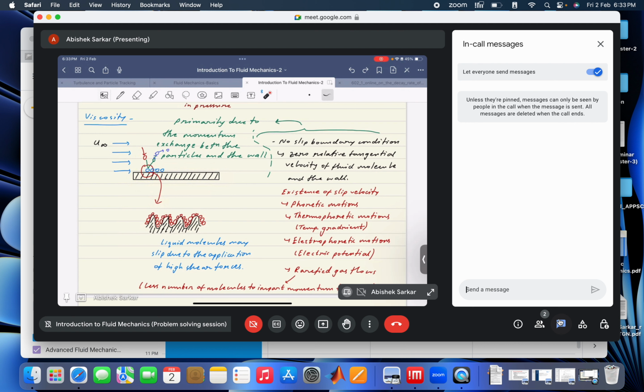Okay, and what you will observe is that in these crests and in these gaps or troughs, there would be some liquid molecules that would get entrapped. Okay, that would basically stick to the surface of this uneven wall. Since there are several other molecules above them, water molecules, liquid molecules to be more general, the molecules above these red molecules are not stuck on the wall. Okay, so they are in motion, they will be moving.